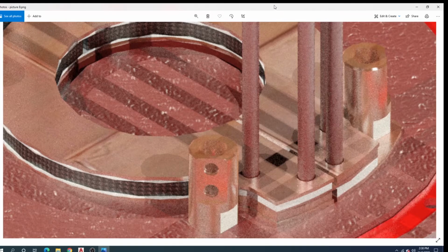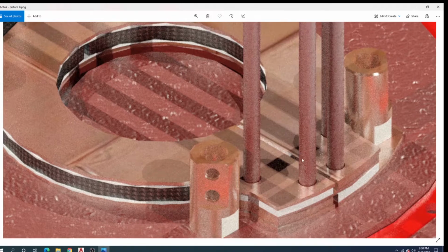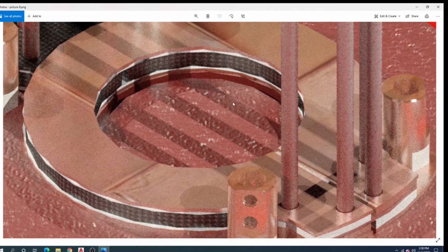They're still coils because electricity is still going in a circular fashion, but it's not a wire, it's a coil, and you have these layers. And I did this because this thing is rated for at least a 5 kilowatt, 5,000 watt output. I designed these coil layers to be able to conduct 100 amps all day long without burning up. That's why everything is so big.